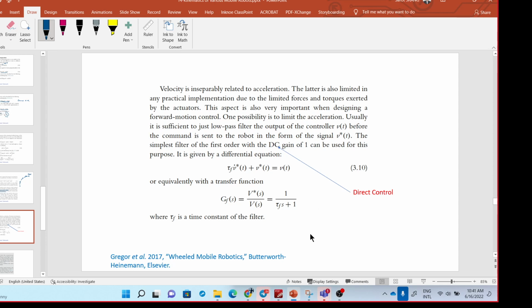At the starting point, the distance from the robot to the goal is very far, so the velocity calculated from the controller can be very large, but then we limit it to the maximum due to the limitation of the actuator. So let's say at the initial time, the linear velocity that we compute from the controller starts at maximum.